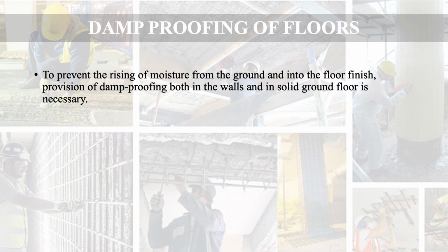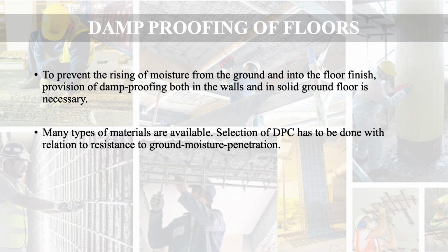Damp proofing of floors. To prevent the rising of moisture from the ground into the floor finish, provision of damp proofing both in the walls and in the solid ground floor is necessary. Many types of materials are available. Selection of DPC has to be done in relation to resistance to ground moisture penetration.